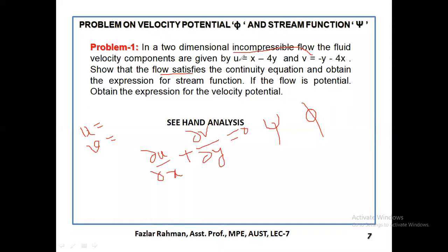So from here, you figure out del u by del x. From here, del v by del y. Then put it over here. If it satisfies this equation, then you can say it satisfies the continuity equation.